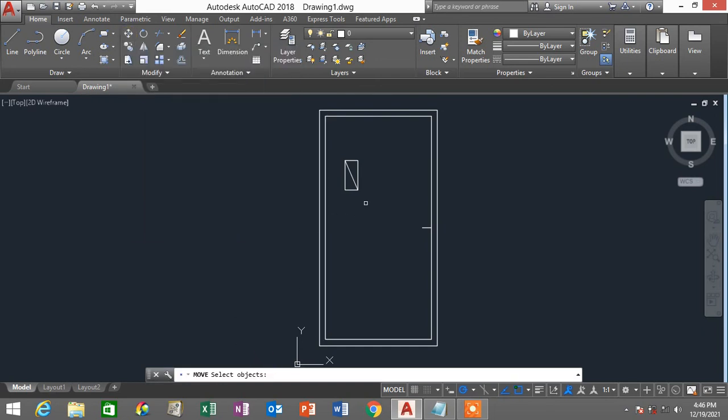You're going to select it, but remember, it's just a single click. If you want to select like this, it's just a single click over there, single click over there. There is no need to drag. After you have selected the object, press enter. And when the command asks you to click for the base point, you just put your mouse on the center of the object, click, and put it on the displacement or destination point over there.